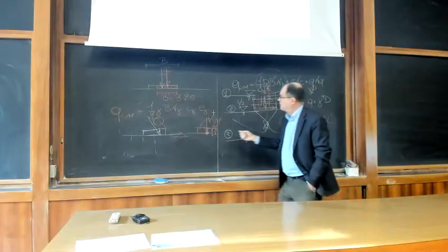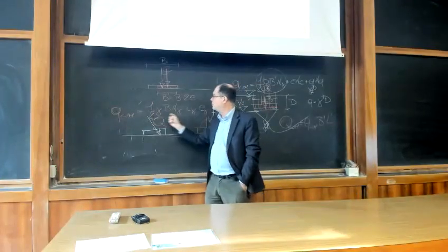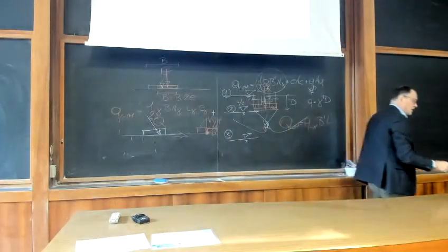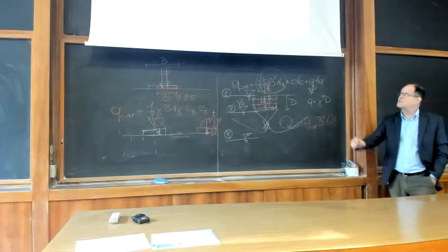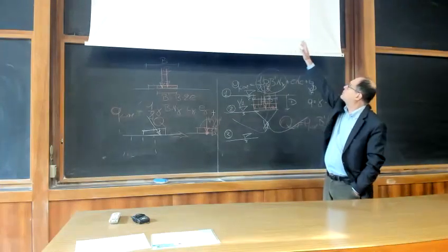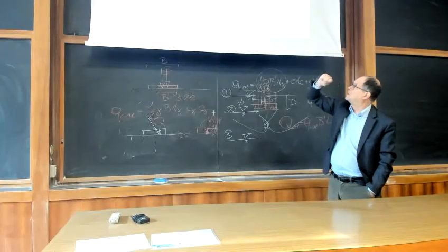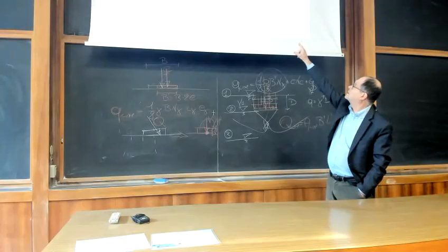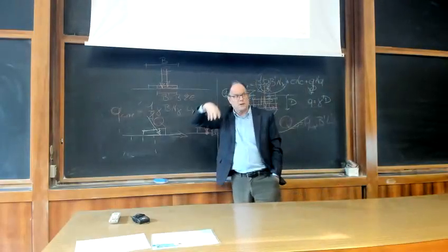And we know from I gamma that actually there is this interaction, because I gamma reduces this value. What is the possible interaction? The possible interaction that you can find, and that we will discuss, is provided by this red line, which is a curve and is the real interaction between H and V. Vm is the maximum value under a pure vertical load.